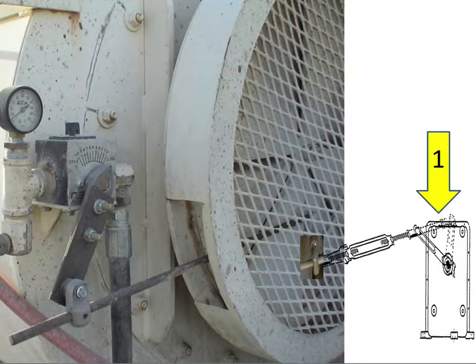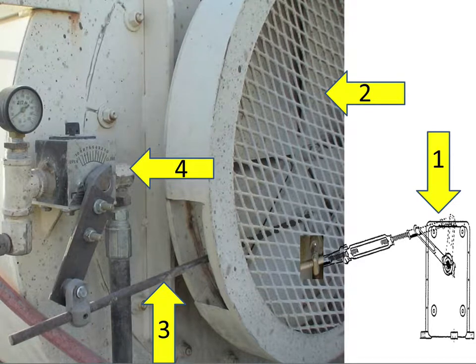Fuel and blower damper adjustment. The burner position motor 1 is linked to air damper 2. The air damper is linked via arm 3 to fuel valve 4. Knob 5 is used to adjust the burner for idling in the low fire position. The low fire position switch is located in the burner position